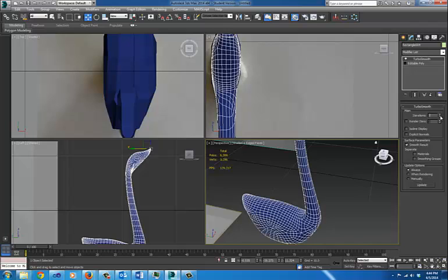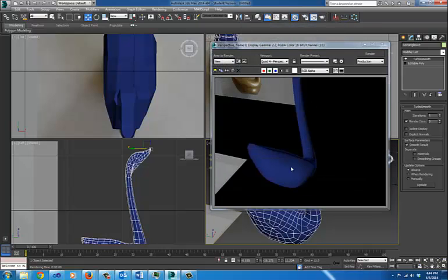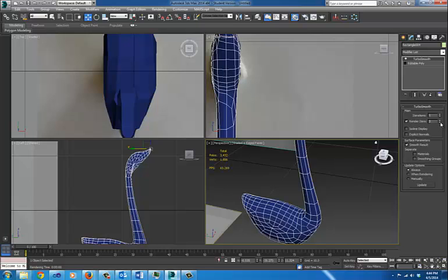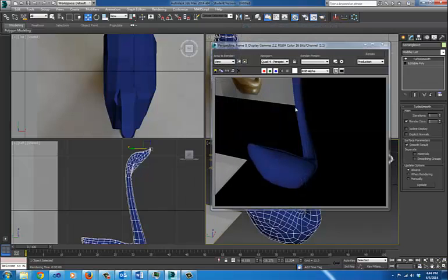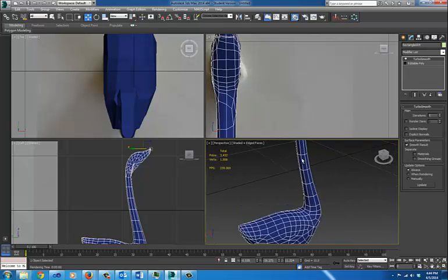If you increase it to probably 4, 5, 6, depending on your computer, you're going to crash the program. You can also create different render iterations, how smooth it's going to render. So for example, we have a very smooth render iteration as opposed to 5 iterations, or if we just use 1 iteration for the rendering, it's going to be a different set of complexity in render or viewport.